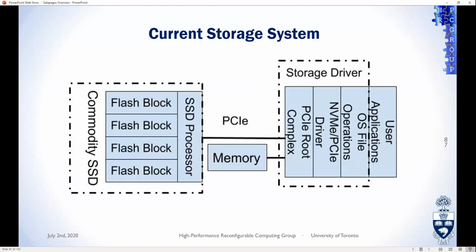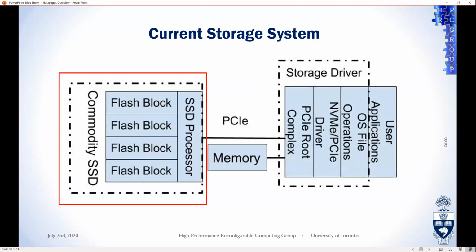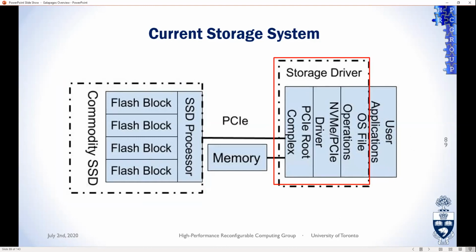Now, this is an image of the current storage system. On the left is a standard off-the-shelf SSD connected via PCIe to the CPU system, which has, at the lowest level, a root complex performing the physical interface. On top is an NVMe driver that handles creating the PCI messages. This is utilized by the OS file operations driver that handles the file system navigation and inode navigation and exposes an API that the user application can then use. This storage driver is incredibly complex, and it is what we aim to simplify so that it can be done